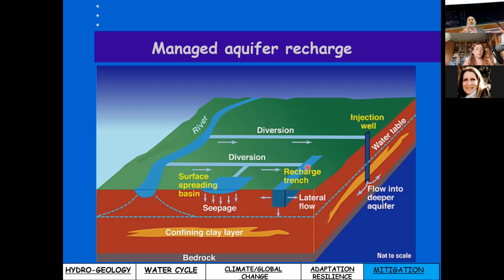And so from a certain point of view, you reduce the risk of the flood because you let the river wander around these areas. And from these areas, at the same time, a certain quantity of water is infiltrating down into the ground, arriving to the aquifer. So you have actually a modification of the hydrologic cycle, in some way inducing an increase of recharge.